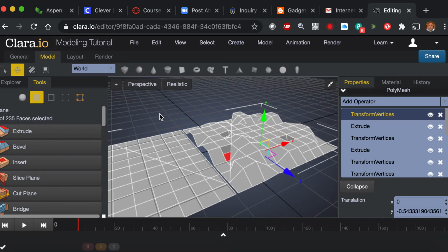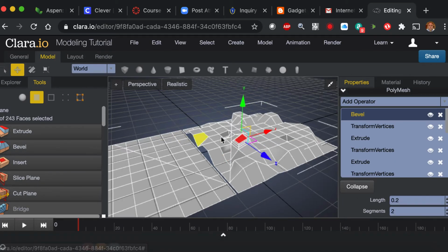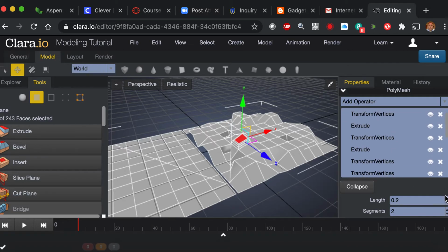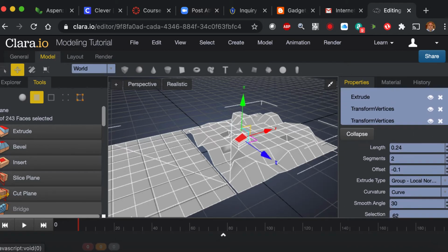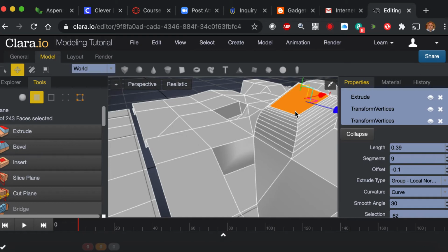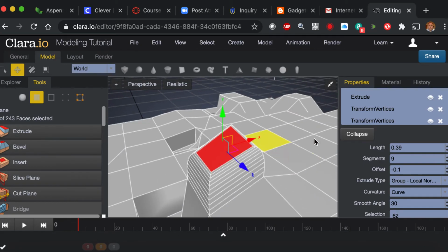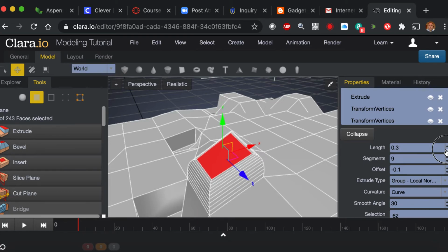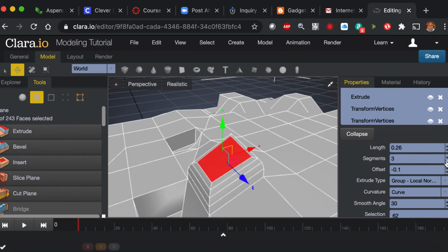And then of course, you can also bevel a component. So if I selected this and I hit bevel, that's going to bring out the whole form. You could increase the length in this editing bar, or you could increase the segments, and that's going to round those edges. This is a great tool for furniture. So if you can see this, I'm going to hit F for framing it. You can change these values of how it's adjusted. Usually you don't want to do any less than 3 bevels to have a smooth curve. That's a rule that is derived from carpenters.